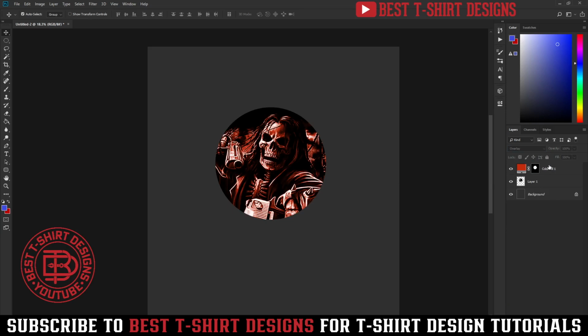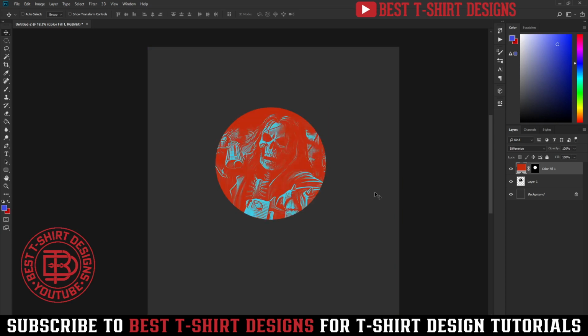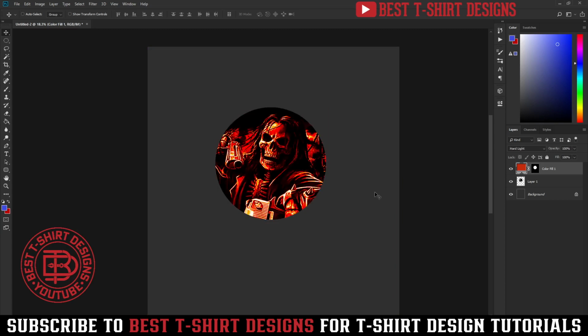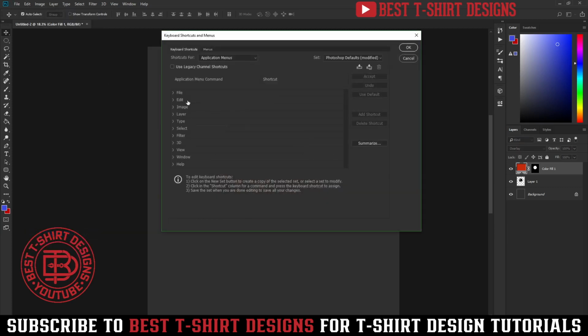And then another thing is, without doing those actions, you can simply, I'm just going back. Okay, so here is a trick. You cannot undo more than once in Photoshop, or you have to press Ctrl and Shift to make multiple undos. But you can go to this edit and then keyboard shortcuts, and from here you can go to edit, then you can change the shortcut.